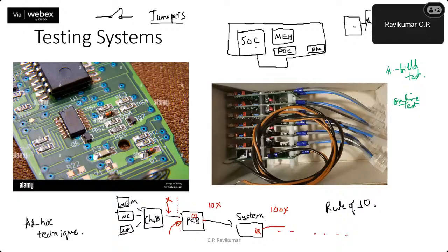Or maybe this is not producing the correct waveform, and as a result, the problem could be here, right? So we could see whether there is any problem here by connecting a different signal generator. So I could connect a signal generator which gives a proper sine waveform and see whether, given the correct waveform, this circuit will correctly function. So we can get access to the input pin of this IC and the output pin of this IC by disconnecting this jumper.